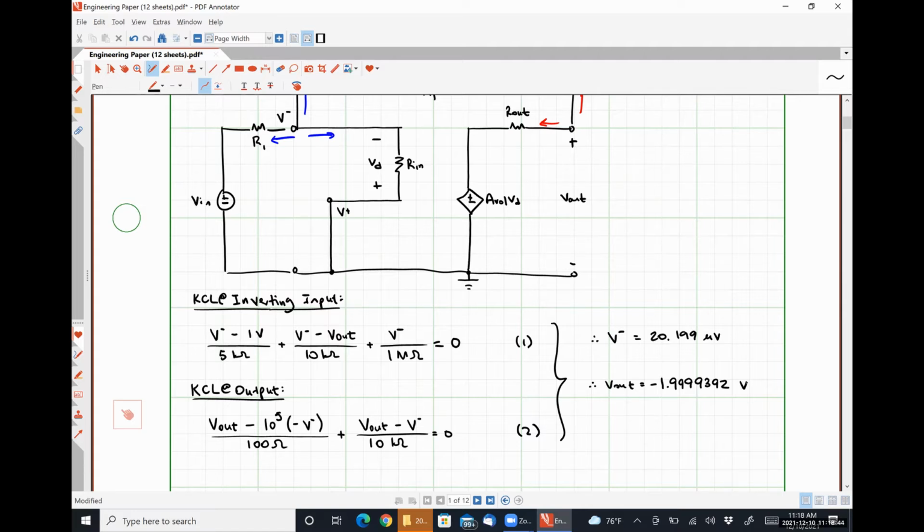We have an input voltage of 1 volt. We have an open loop gain of 10 to the 5, or 100,000, which means that we would expect the output voltage to be 100,000, but we know that can't be true. Okay. So what negative feedback is doing is bringing that open loop gain of 100,000 down to a manageable level so that we have linear amplification occurring.